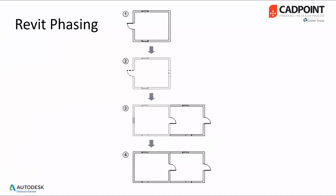We will now look at Revit phasing. Many projects such as renovations proceed in phases, each representing a distinct period in the life of the project. Revit tracks the phase in which views or elements are created or demolished. You can use phase filters to control the flow of building model information into views and schedules. This allows you to create phase-specific project documentation, complete with schedules.